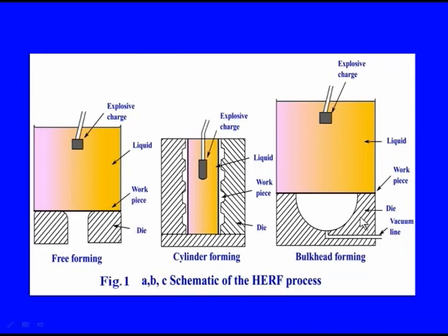However, if the volume of this is large, then the air or the gas entrapped in this needs to be evacuated, otherwise there will be non-uniformity in the shape. Therefore, there will be some connections through which the gas or the air entrapped here will be evacuated prior to the process, so that the shape inaccuracy will be minimized.